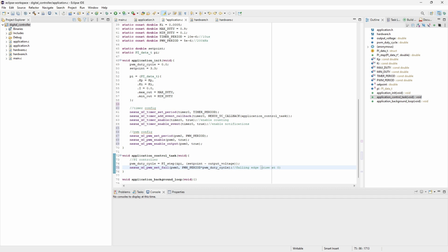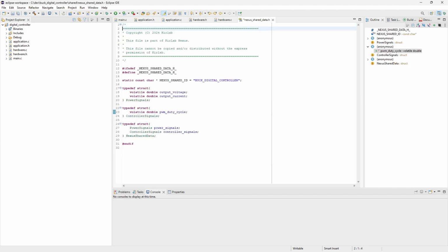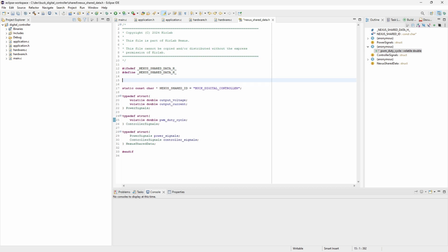The synchronization step, or even the step of the microcontroller simulation, are not small enough to provide all the detail needed in this case. So we will use an auxiliary PWM module that will execute at the Plecs model, and will be managed by the digital controller process. For that, we will edit the shared header and add a PWM link instead of the duty cycle.